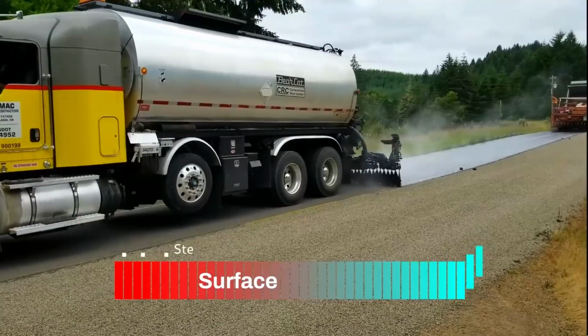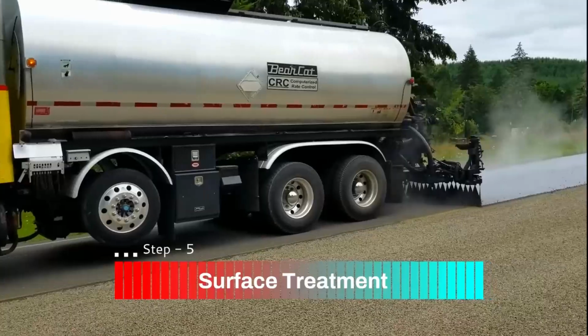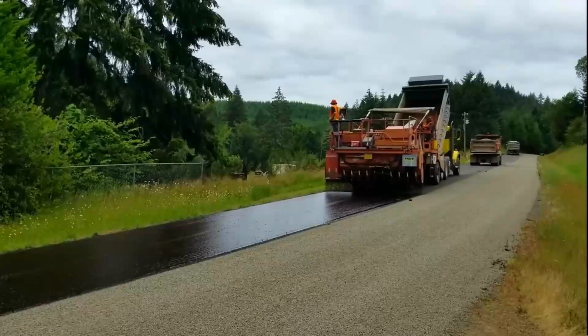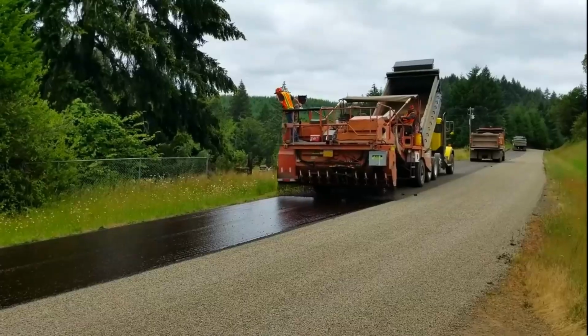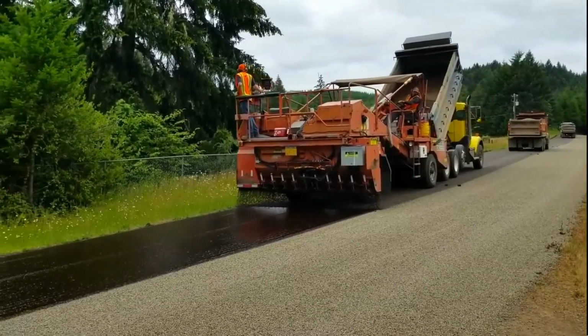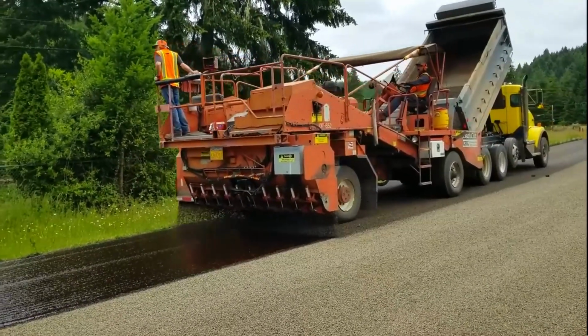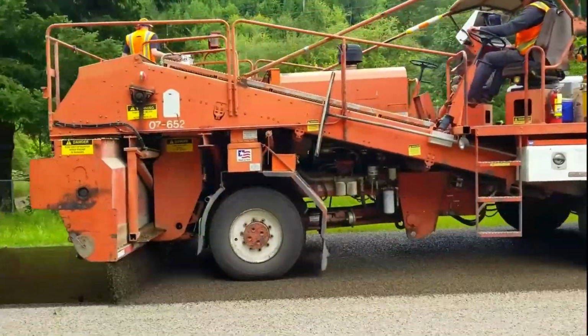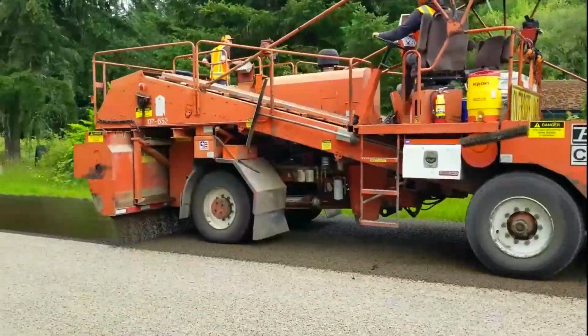Step 5. Surface treatment and curing. A seal coat or tack coat is applied for better bonding. The surface is cured for at least 24 hours before adding the final asphalt layer. Cold in-place recycling is a quick and cost-effective solution, especially for rural roads and urban streets with moderate distress.